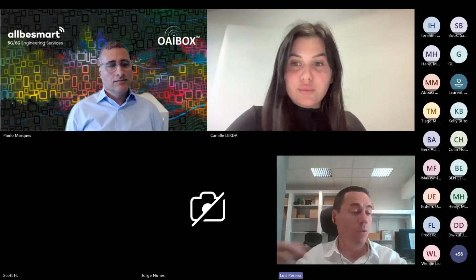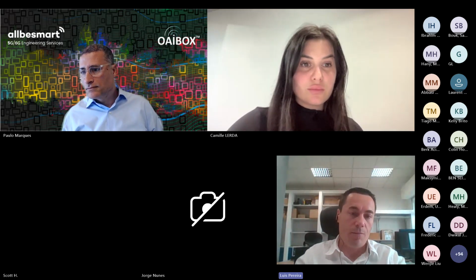Using the DMRS, Luis. Yeah, so as I just mentioned, if you use the OAI UE, for example, you can use SSBs that are broadcasted, so the UE doesn't need to know any configuration from the cell. Of course, if you want to use the DMRS, then the UE needs to be connected, but it can be used, yes, both for the DLSCH or the ULSCH, depending if you are using the signal on the UE side or on the gNB side. So both can be used, it's just a matter of the use case.